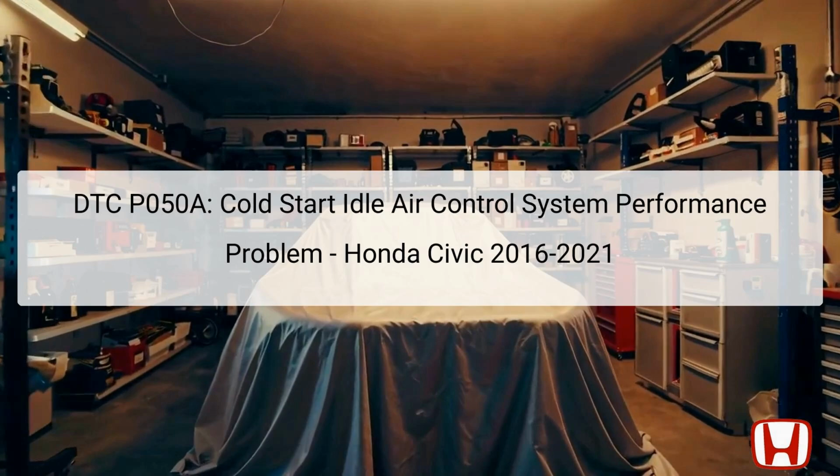Diagnostic Trouble Code, DTC P050A, refers to a performance issue with the cold start idle air control system in the Honda Civic models from 2016 through 2021. This code indicates that the engine control module, ECM, is not receiving the expected signals from the idle air control system when starting the vehicle in cold conditions.